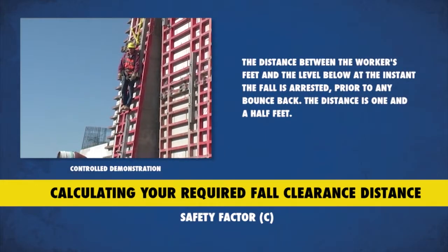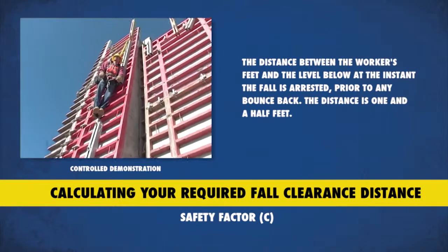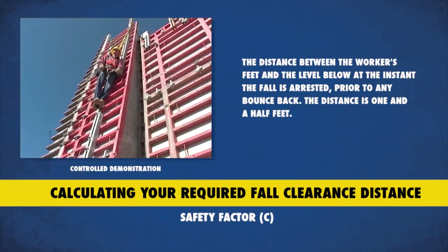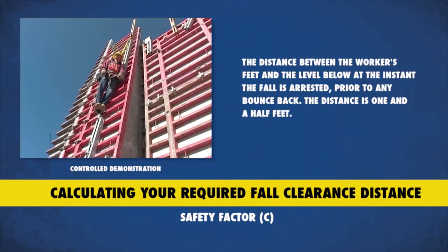The safety factor is defined as the distance between the worker's feet and the level below at the instant the fall is arrested, prior to any bounce back. The typical distance is 1.5 feet.